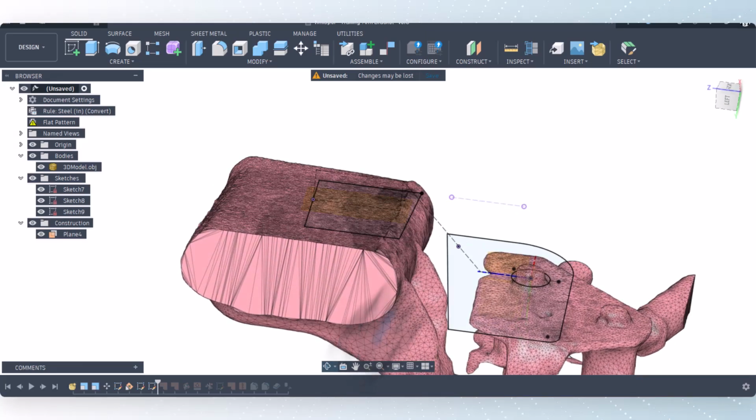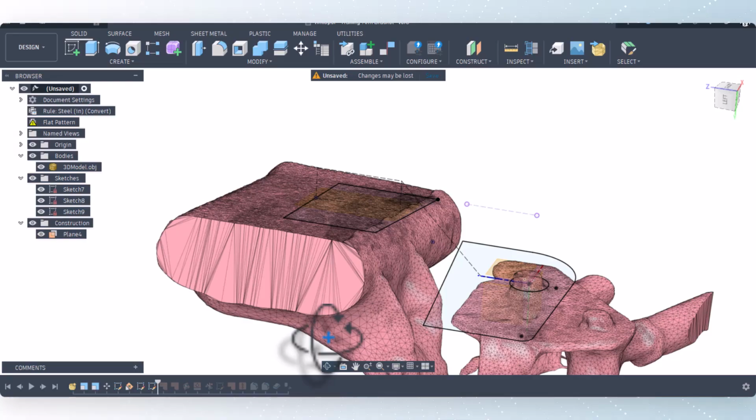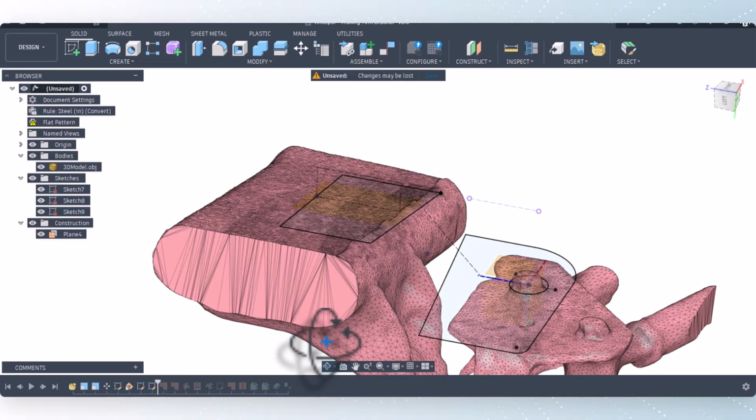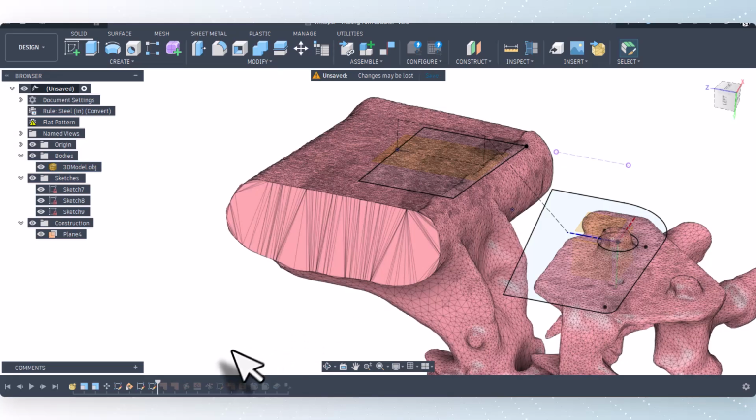So first I took the vertical or horizontal constraint off this line and just dragged it to approximate position. In the same way on this one, just dragged it to approximate position. And then I put in some logical dimensions to lock that into position once I thought I had it close to where I wanted. And of course, those dimensions that I put in can be edited.